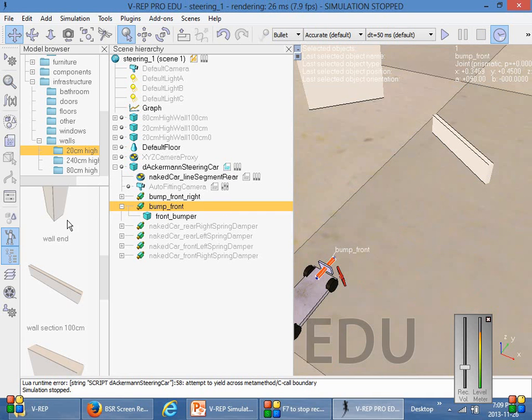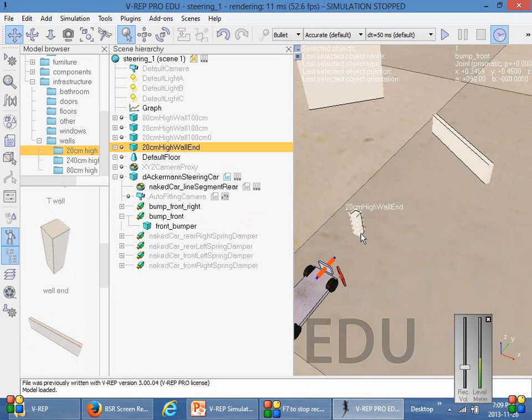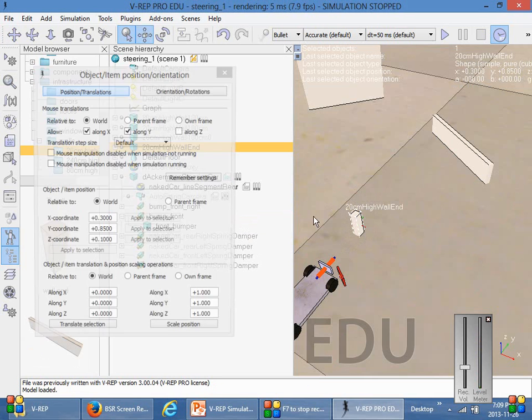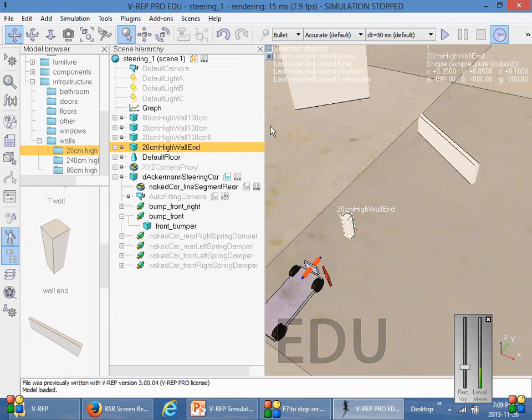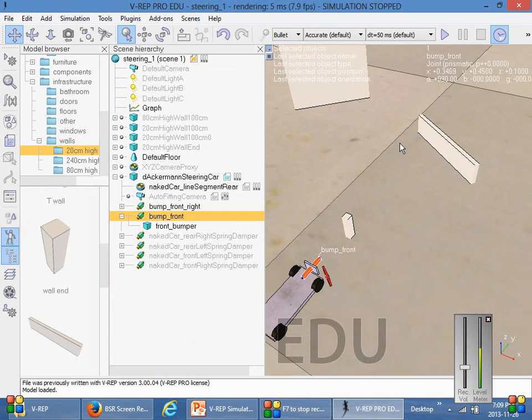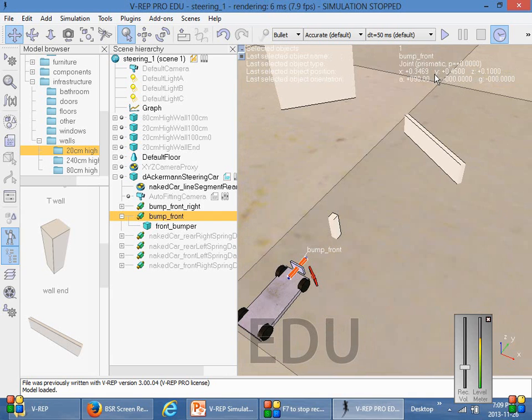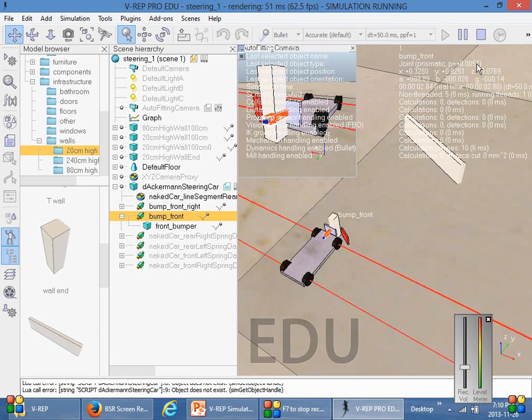So one thing we'll do, we'll actually put a wall right in front of it. Okay. And when you click on the name of it, you will see some of its properties shown up right here in the environment. You have the name, the number of selected objects, and there's also this object type, a prismatic joint, and you also have this p-value, and this p-value is its current position. Now, if you run this system, you'll find that it went from 0 to 0.05.